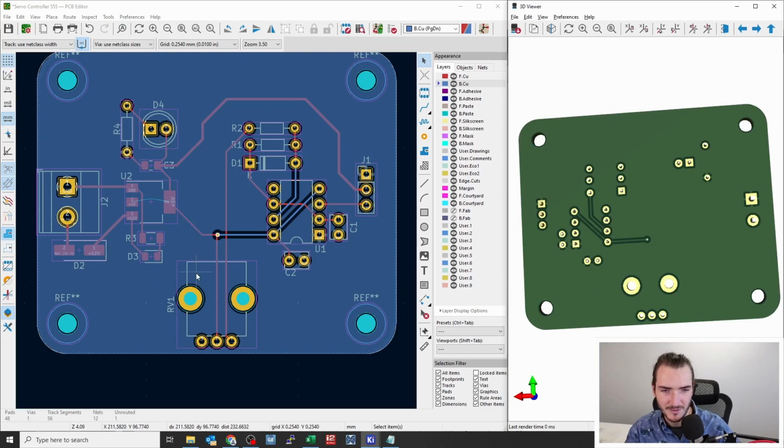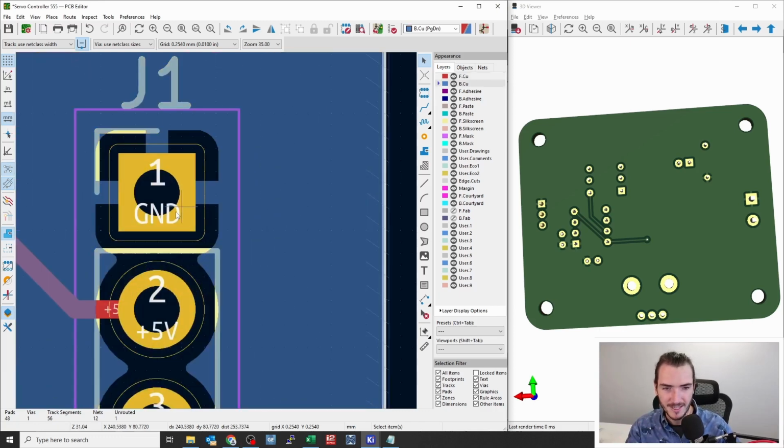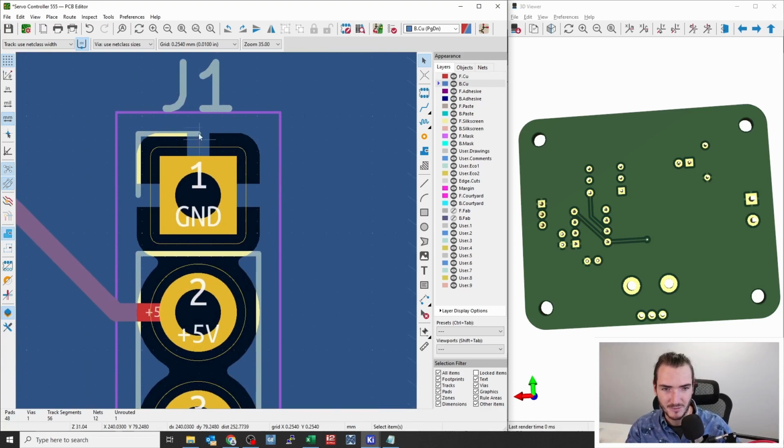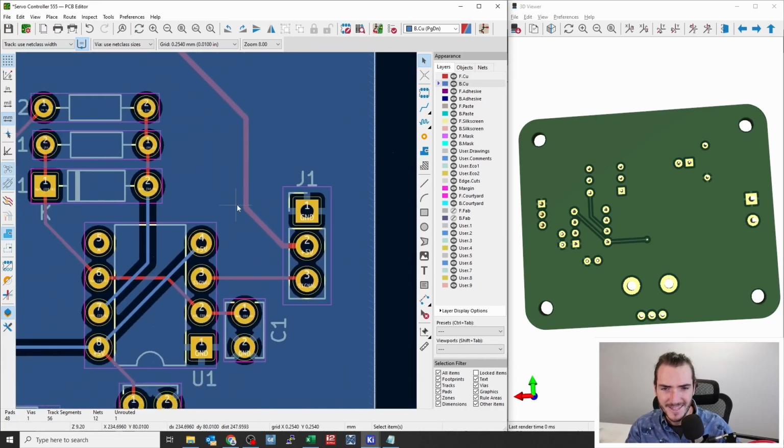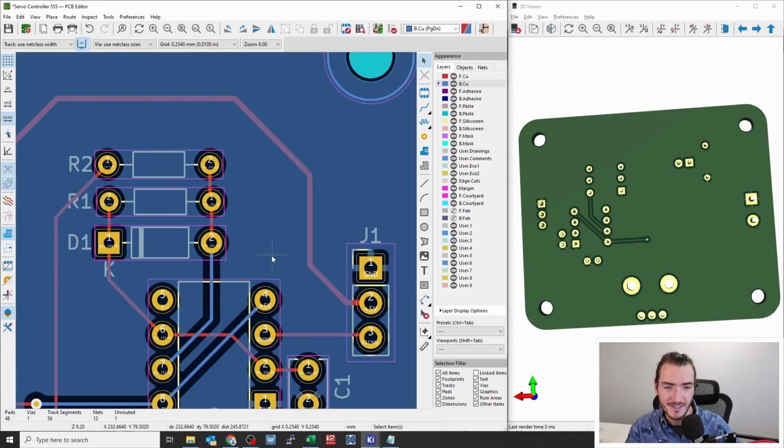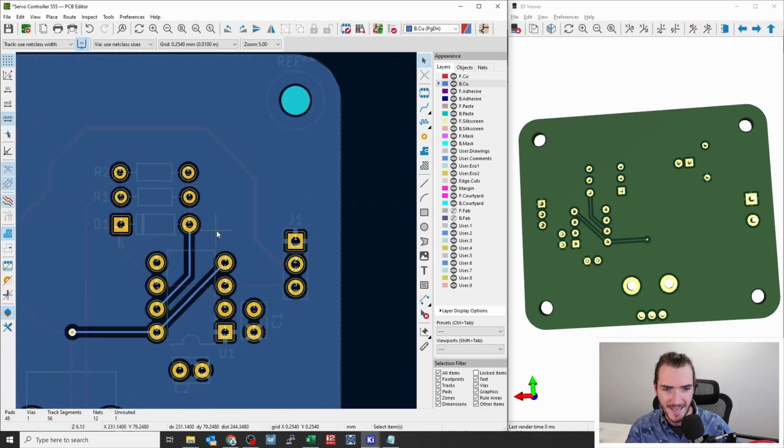And that's why I wasn't really bothering with doing the ground pins before, because I knew I was going to work with a lot of through-hole parts and execute that fill. So now when we zoom in on a ground pin, we can see it has this breakout. And again, things are getting a little bit noisy, so we should enter high contrast mode with H.